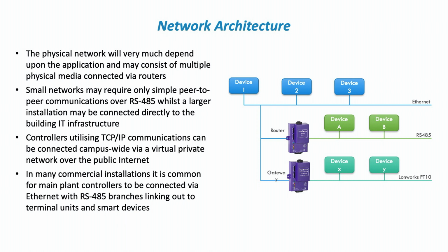If you then wanted to communicate with other devices, which were also using the same protocol, so we'll assume we've set this up to work with BACnet, then you need to move from Ethernet onto RS485. So you would have to go through a router. If you're using Trend, then presumably you'd use something like an IQ4NC to do this, provide your routing. If you were using just a non-proprietary BACnet system, you could use any BACnet router to take those BACnet packets onto RS485.